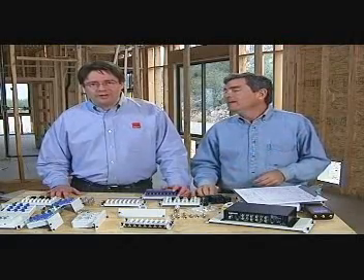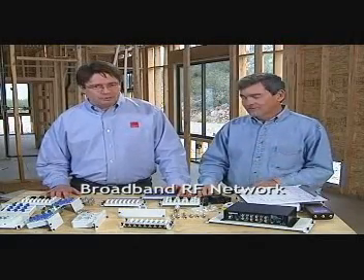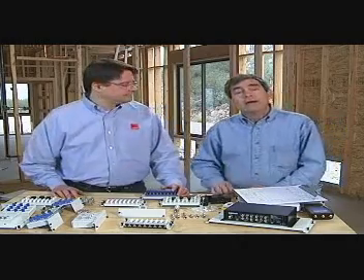Next, we need to design and specify the RF broadband distribution system. Now, the goal is to combine the external sources with all the in-home generated sources and distribute the combined signal at an adequate signal level at all external outlets. The first step is to itemize the external source inputs that we need to support. In our case, we plan on using cable service as our primary source with the pre-wired option for off-air digital television. We also plan on supporting satellite, but we'll talk about that later.